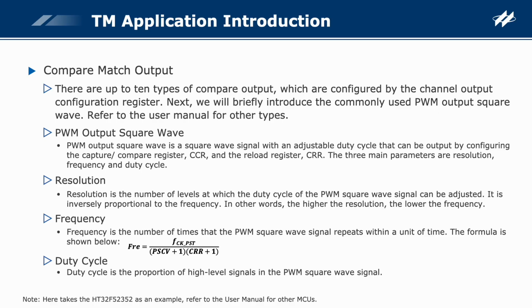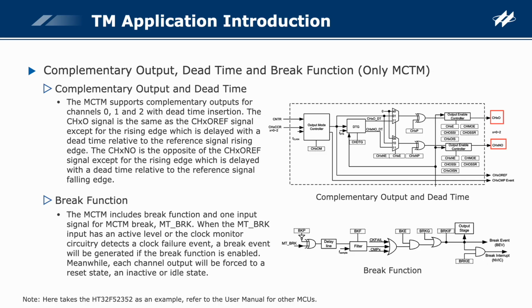Duty cycle is the proportion of high-level signals in the PWM square wave signal. The following functions are only supported by the MCTM: complementary output, dead time, and break function.